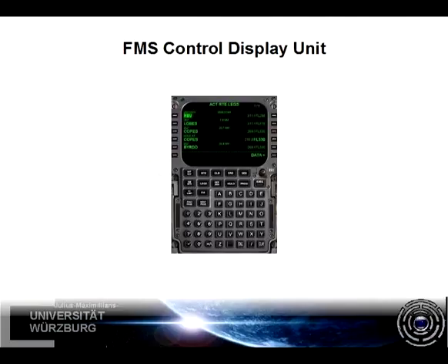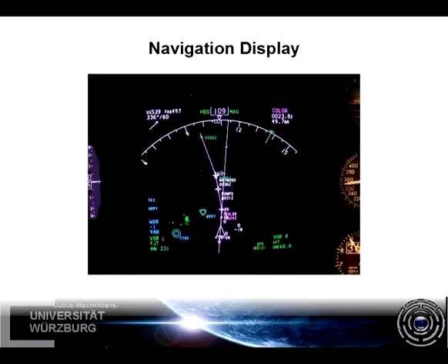The keypad and display that is normally associated with the FMS gives the pilot the ability to enter a flight plan that contains the departure, routing and intended approach. In flight, the FMS will present the route and other relevant information like the distance to the next waypoint and currently close by airports on the navigational display. You can also see the aforementioned wind vector in the corner.